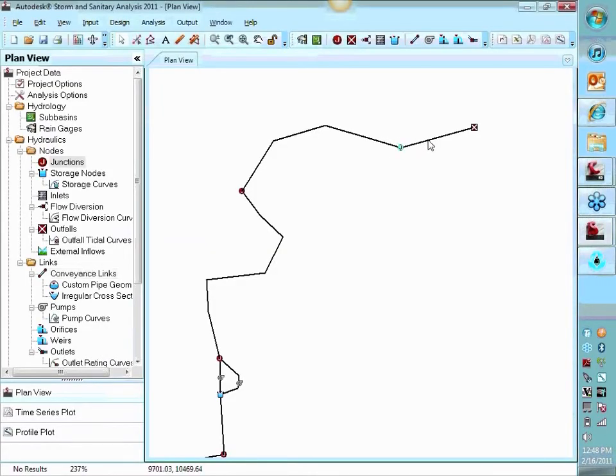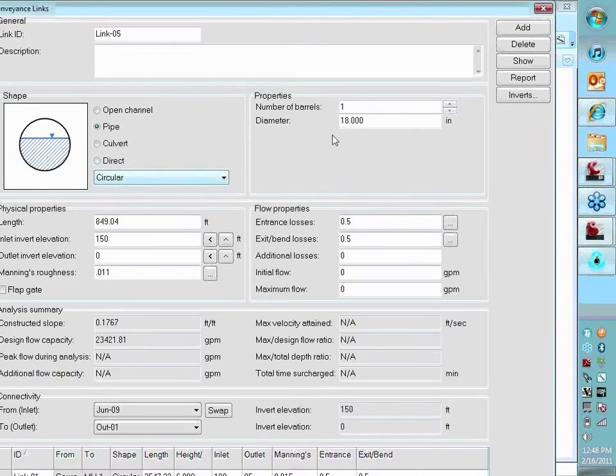And we're at 150 here, so then let's drop down. Let's say this is just an outfall. It goes into a manhole there, and then from that manhole directly gravity flows into the pump station. So let's say it's a 12-inch pipe. Culvert, it's 150, and then let's say it's 149.